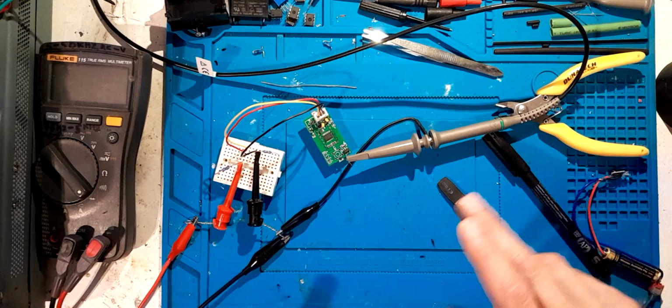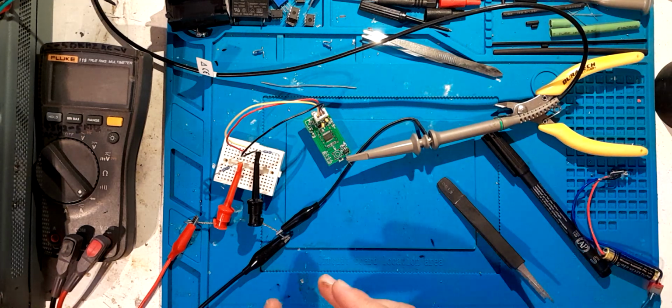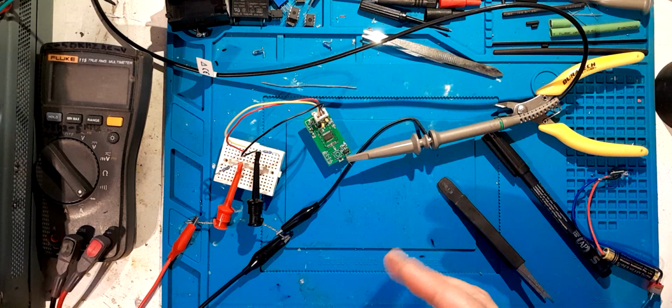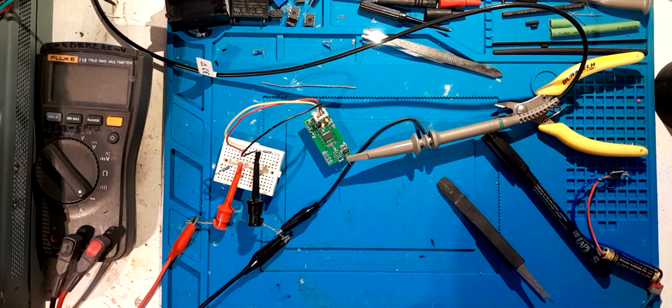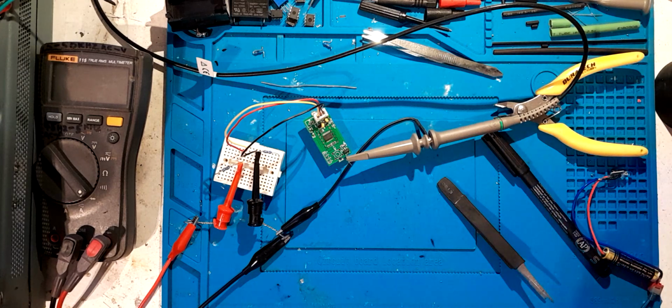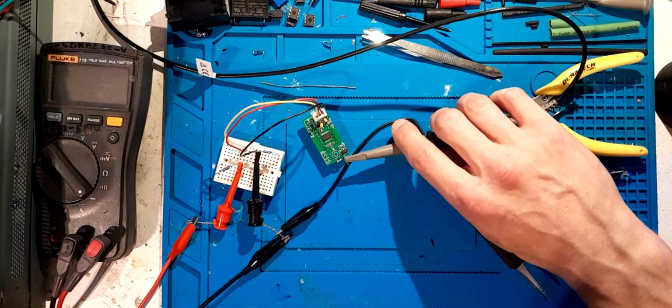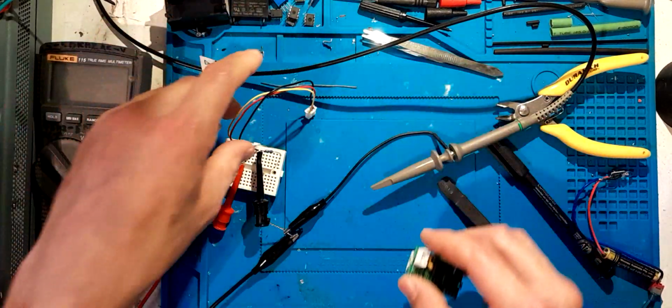But I think it goes in the opposite direction. So when it's all the way down, it's 1 millivolt too low, but when it's turned up all the way at 30 volts, it's like 2 millivolts too high. That's what I mean by non-linearity, and all this oscillation could be causing that. So it's all well and good to be like, ah, it's good enough, whacking it in. No, because if it's not bang on perfect, that oscillation could be playing with it and affecting the actual precision of the device.